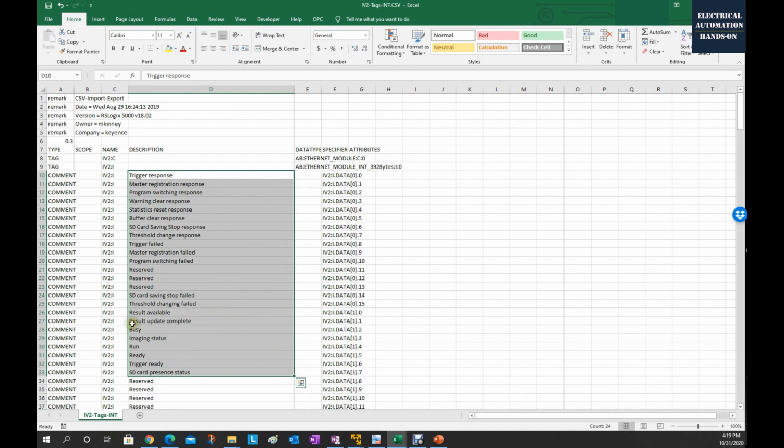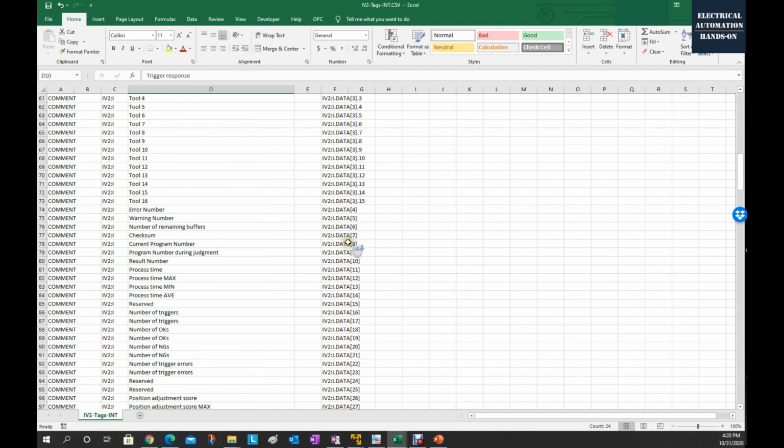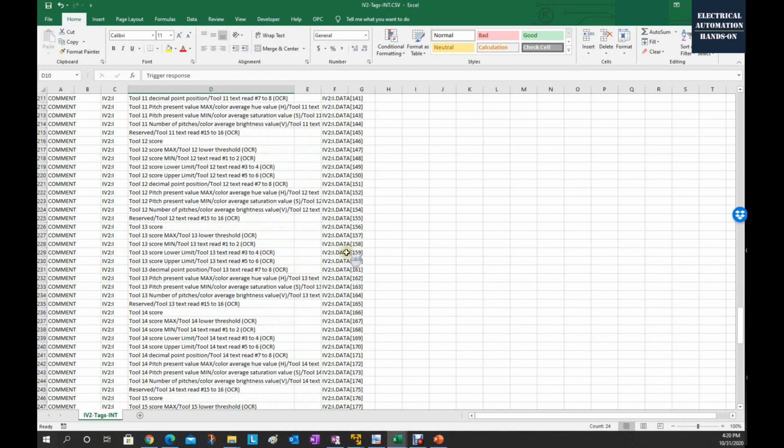To join the tag name and this address together, in most cases we will use the COP copy. We will firstly create the UDT structure and create the tags based on this structure, and then use the COP copy to copy the input to this tag structure, and copy that structure to the output based on the output tag list.